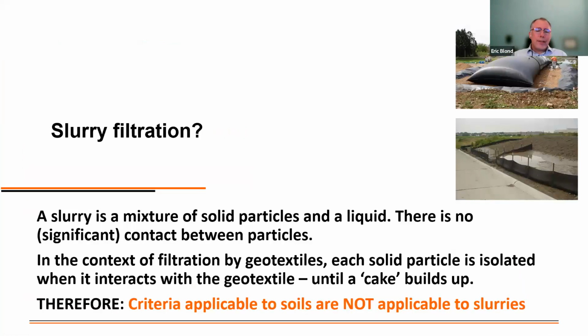Slurry filtration, as I said, I am not covering this topic really because it's completely different. A slurry is a mixture of solid and liquid. There is no significant contact between particles traveling in the fluid, and each particle reaching the fabric is isolated, and a cake will build up eventually. What's important to remember is that the filtration criteria that we use for soils are not applicable to slurry filtration at all.